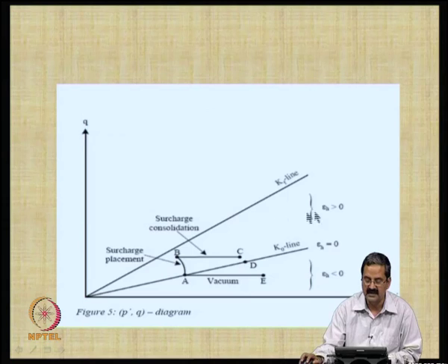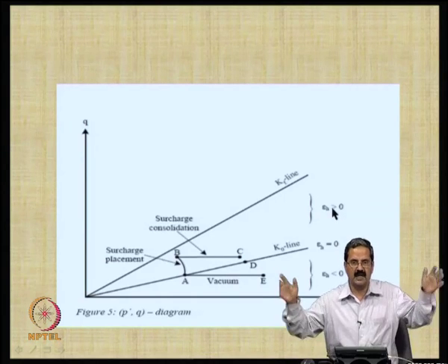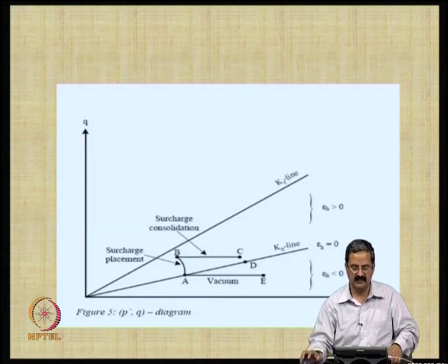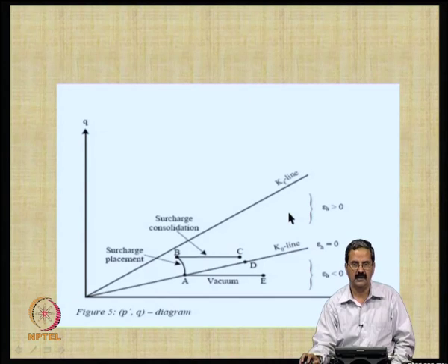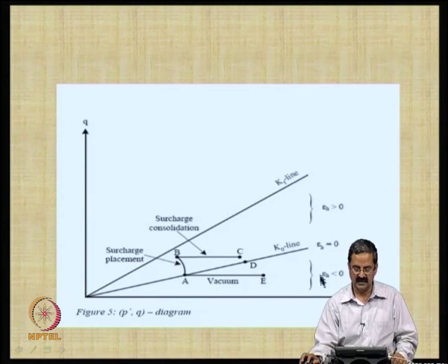You can see that there are always some horizontal strains there, because the moment the soil state is in this range, there are always some horizontal deformations. But if the horizontal deformation is too much, then total collapse takes place, right. The horizontal deformation should not be too high, because it is a combination of shear and volumetric strains, and it should not lead to failure. So, this is a region in which horizontal strains are higher, and this is a region along which horizontal strains are 0.